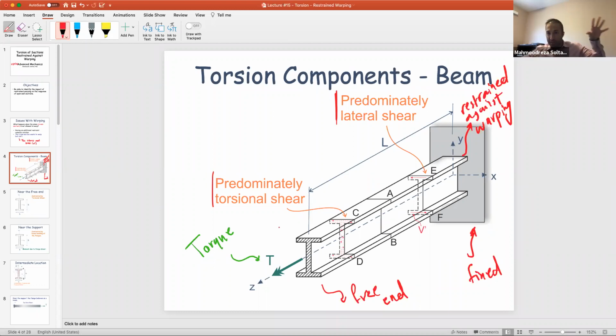Now the classic torsion would be more effective compared to the warping that you had to the right side, okay? So as we discuss, for example, from here to this length, on this length, we are defining alpha, right? And this alpha on the length, up to this length, that's what I'm trying to say, okay? On this length, you need to consider the effect of warping stress, from the fixed end, the distance from the fixed end. After this point, all the way to the free end, now you're dealing only with the torsional shear stress, okay?